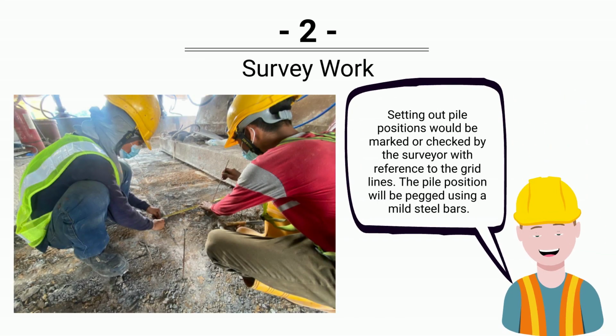Survey work. Setting out pile positions would be marked or checked by the surveyor with reference to the grid lines. The pile position will be pegged using a mild steel bar.